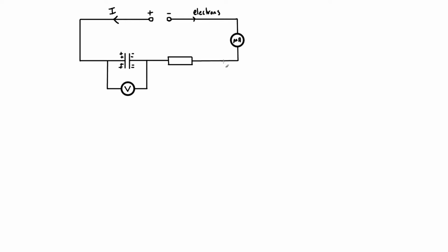continuation of the drop in the current within our circuit, until of course eventually we're going to arrive here with the capacitor fully charged, and at that point then the potential difference across the capacitor will match the EMF of the power supply. There will then be no volts across the resistor at all, and at that point then the current in the circuit will have dropped to 0, and we say, okay, we've fully charged our capacitor.